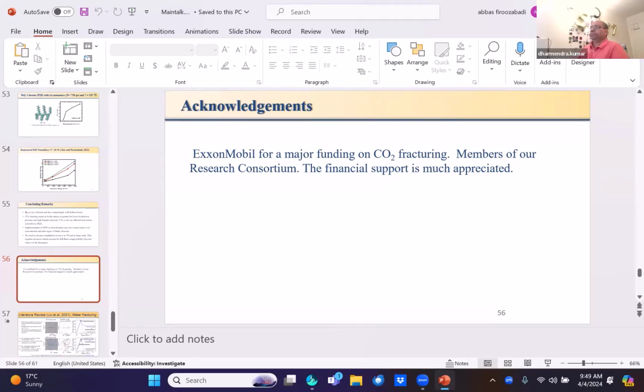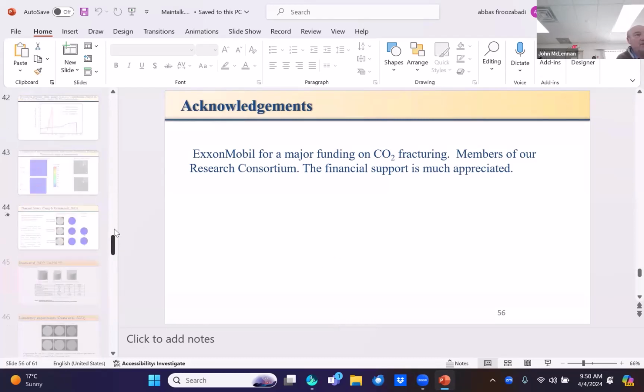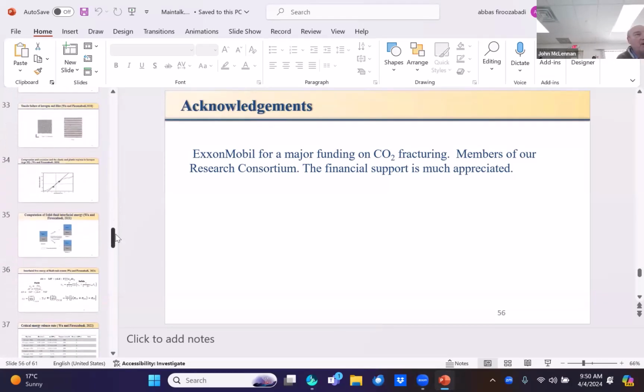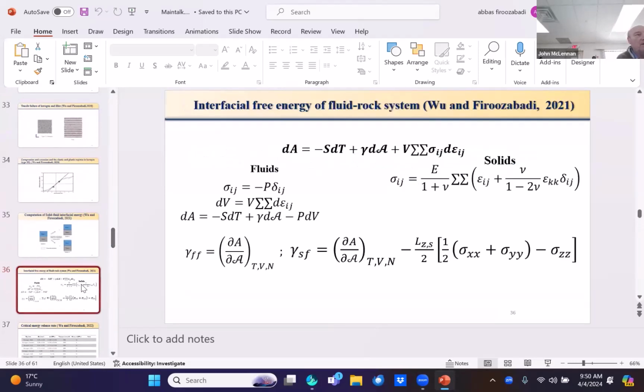Yeah, very good. And so Yoshioka has a couple of questions, and they mainly relate to strain energy release rate as I see it here. He's interested in slides 36 and 37, where you're calculating G sub C. Do you calculate the strain energy release rate by breaking the atomic bond between the solid with fluid saturation? The slides seem to suggest that it's computed by the areal change due to deformation.